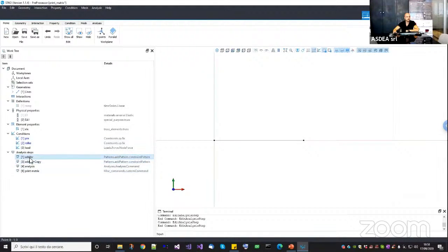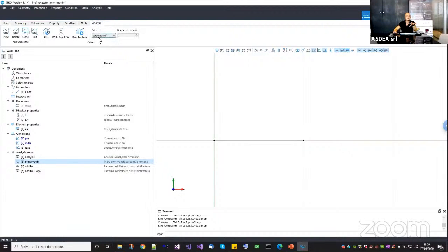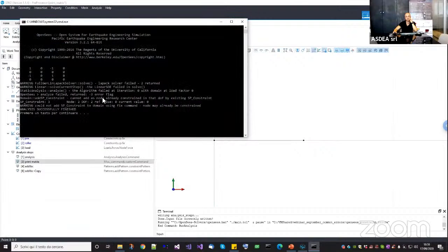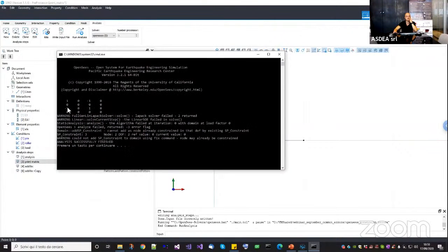Let's say, for example, that you don't want to use any boundary constraint. For not using it, I can move it to the end in such a way that my matrix will be singular, of course, because there will be no constraint. But at the point that I print it, you will see how the entire stiffness matrix looks, so the original unconstrained matrix. Of course, the analysis here will be singular, and this is the 4 by 4 matrix that we expect.